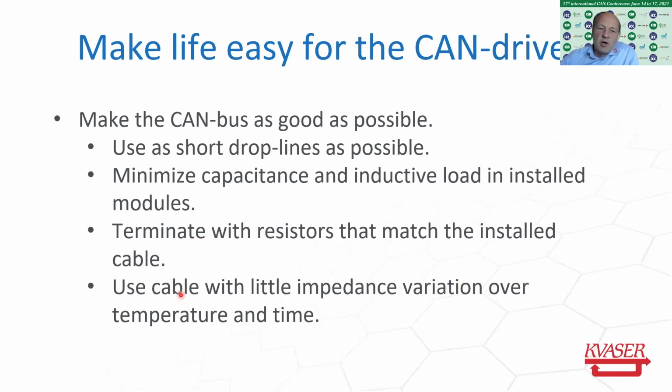The next point is to use cabling with very low impedance variation, so it doesn't change with temperature and time. PVC, for example, is an insulation material that changes the impedance dramatically at low temperature, and that could be a problem. You should at least test that your system is still working with a cold cabling system.